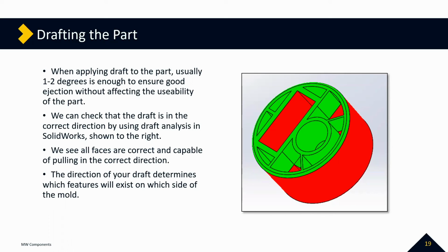Yes, it can be on the edge of a part, just along the edge of the part, if I understand this correctly. So on the outside, you can have a full parting line where the only issue is this undercut right here. But if this whole thing could all be on one side of the part, you could just make it all on a single